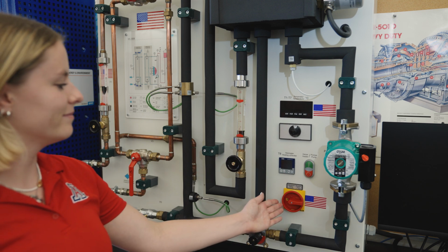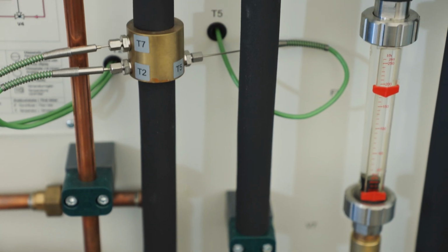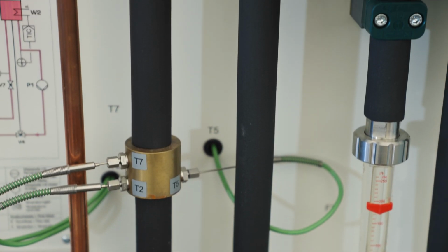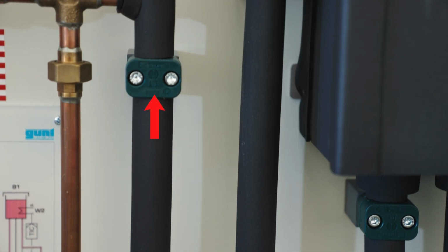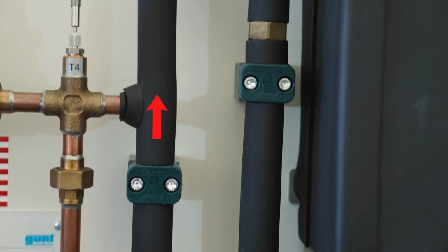Knowledge of the fluid temperatures, fluid property, wall temperature, and volumetric flow rates allows for the calculation of characteristic parameters of the heat exchanger. We will now review the main components and controls of the heat exchanger WL308. The main switch powers the system on. The concentric double pipe acts as the heat exchanger. The inner tube contains the hot water, which always flows upward. Cold water flows in the surrounding outer tube.